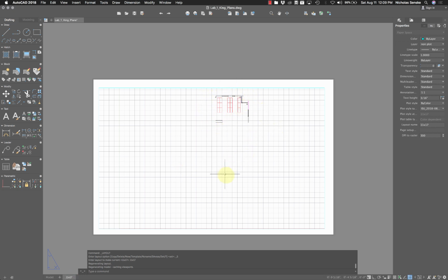You can see here, it's actually kind of small right now. We're in the layout view. We need to look at a scale. We need to choose a scale for the drawing. Every drawing has a scale because you can't print a drawing that's the same size as the space that you're going to build. It just makes sense, right? Plans are smaller than the thing.